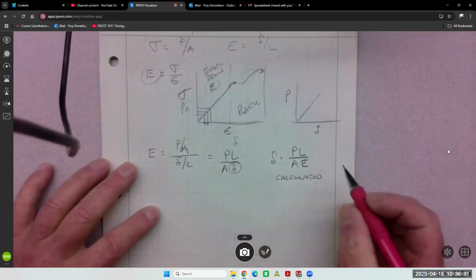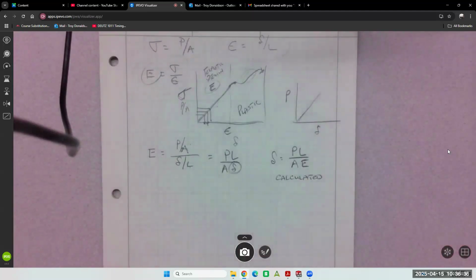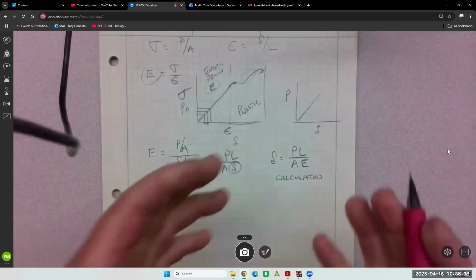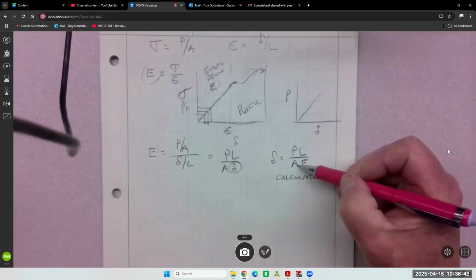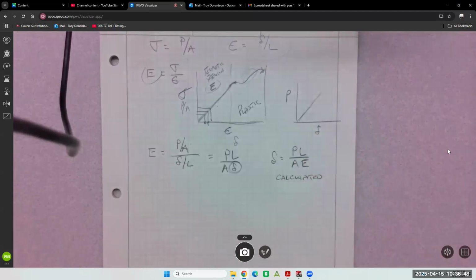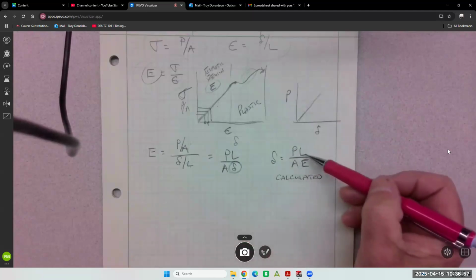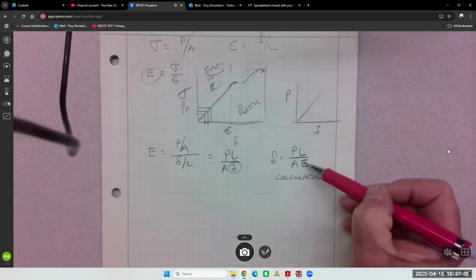Which means I'm not putting in any kind of a limit stress. I'm calculating the stress and putting it in. The stress is in there because P over A is in there, right? And the strain's in there, this L and E thing, it's all in the package. The thing is, you've got to know four things to get it: load, length, area, and what material it is. This is the material property.